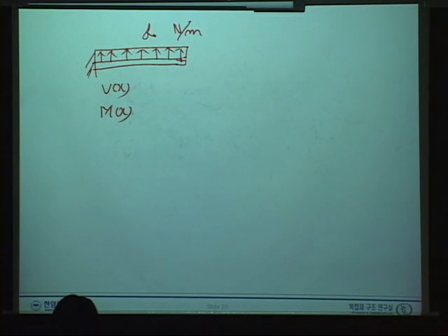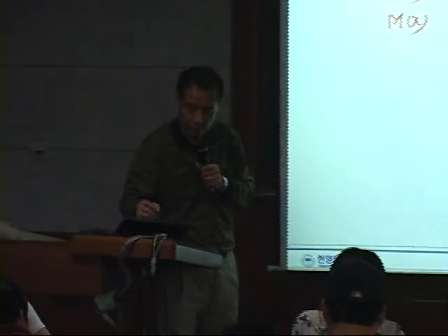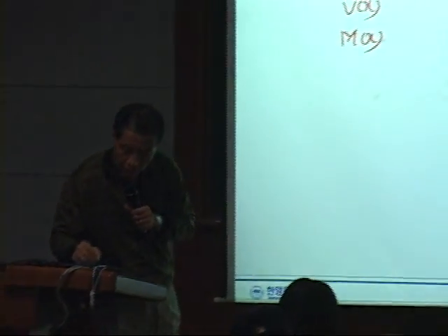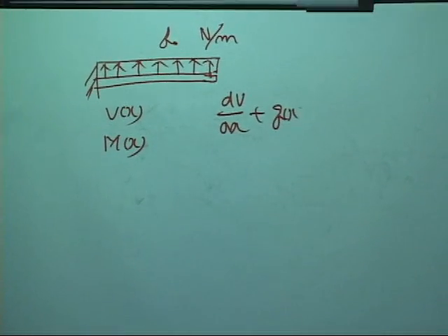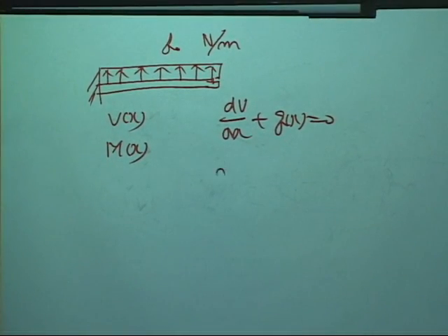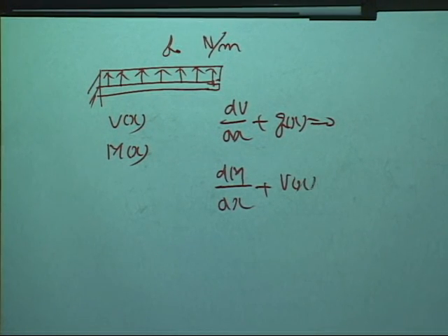And remember there's a differential equation, one governing the shear force, dV/dx plus q(x) equals 0, and the other one is dM/dx plus V(x) equals 0.